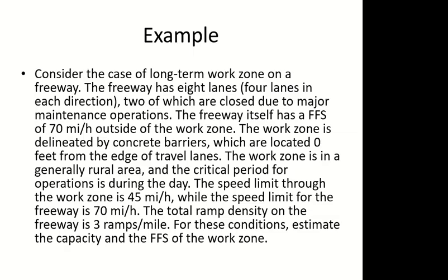The same applies to work zones as well. If I have a work zone which has a duration of 1 day, should I calculate the work zone factors because of 1 day, or should I focus on the rest of the 365 days? The answer is I should focus on the rest of the days, not the 1 day of the work zone. A work zone is like an anomaly, something rare, something exceptional. So we look for normal conditions. If the normal conditions have that weather or that work zone, then we will consider it.